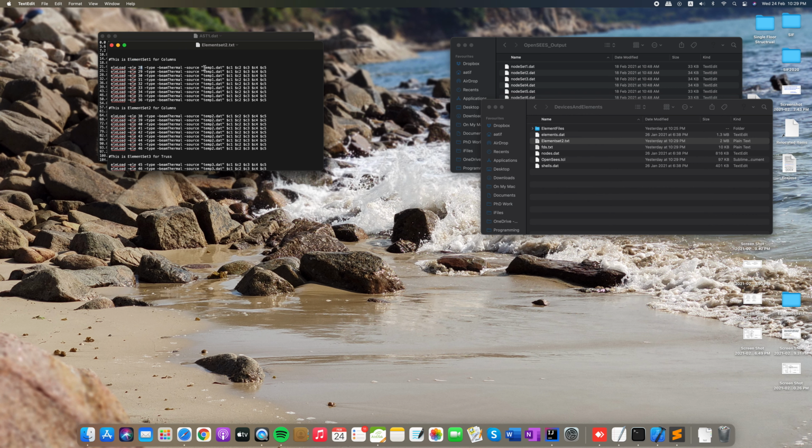The file name is temp1 for elements within this range, and for FDS device 2 it should be temp2. In this way the temperature will be mapped directly from FDS to the file for structure analysis, to each element.